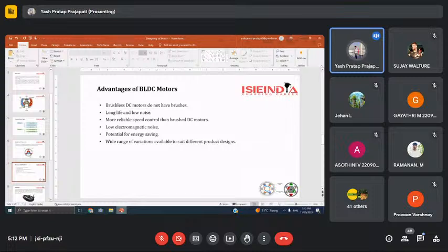With a brushed motor, the brushes and commutator wear down as a result of continuous moving contact, and also produce sparks where contact is made. Electrical noise in particular is the result of the strong sparks that tend to occur at the area where the brushes pass over the gaps in the commutator. This is why BLDC motors are often considered preferable in applications where it is important to have low electrical noise.